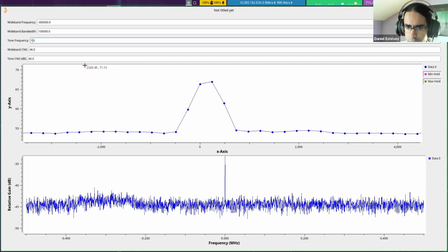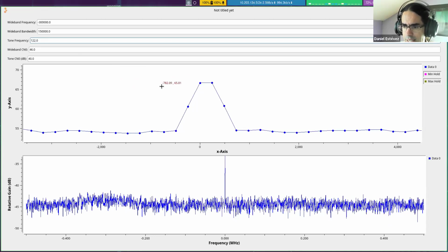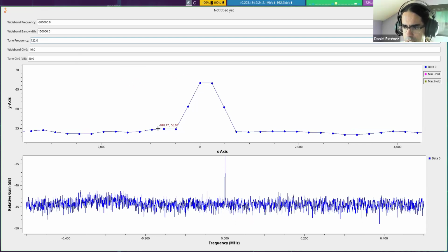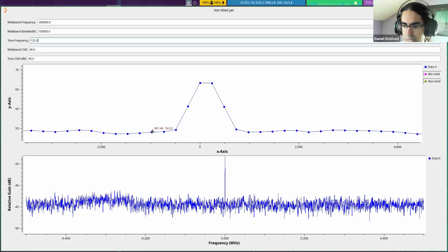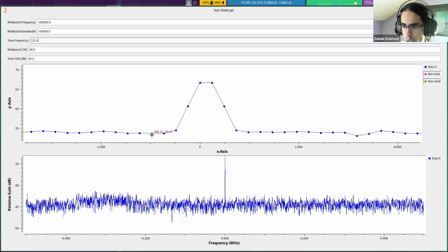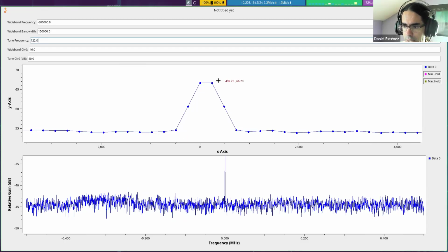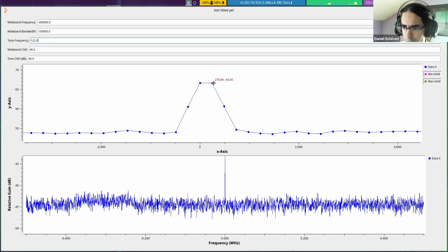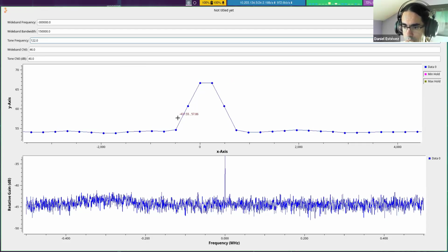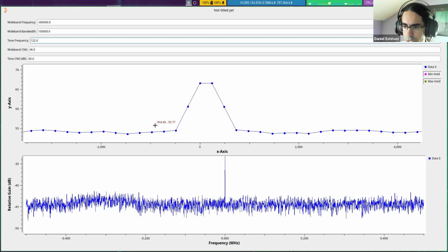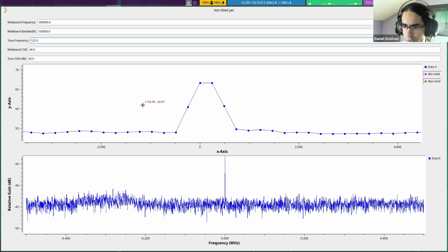That was 122 to get it exactly halfway. That's kind of bad luck, since in principle we don't control the frequency of the signals we will be receiving, but it's something that can happen, and sometimes you need to prepare for the worst case. The reason why we have less power on this is because the power has been distributed. The total power needs to stay the same. That is a property of the Fourier transform.